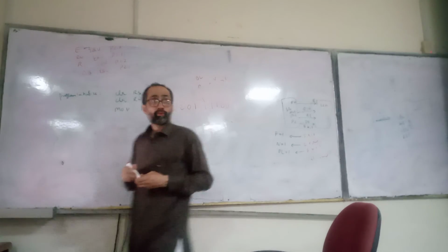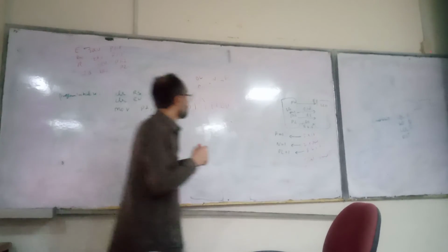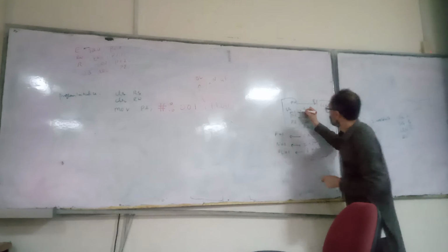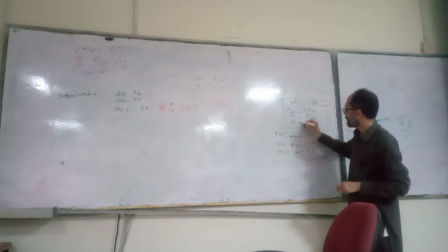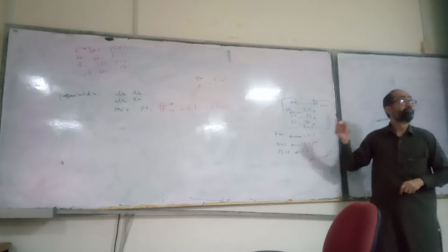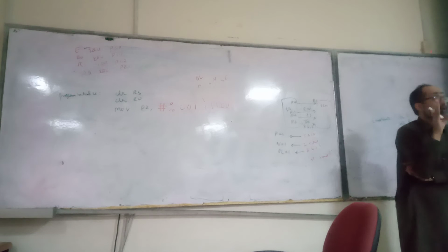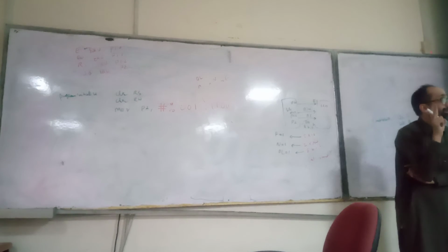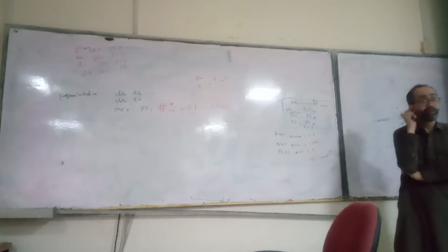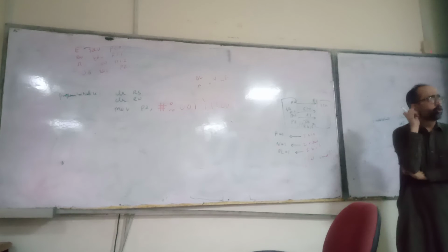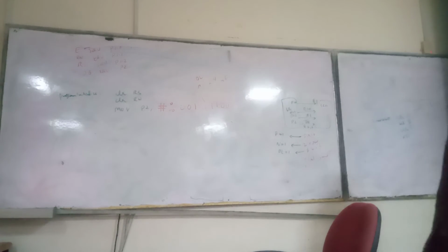Okay, now we have set these signals. This is 0, this is 0, and this is all the commands. But this data will not be accepted by the LCD. Why is it not accepted? Because you have not given a pulse. Now you should give a pulse. How can you give a pulse?